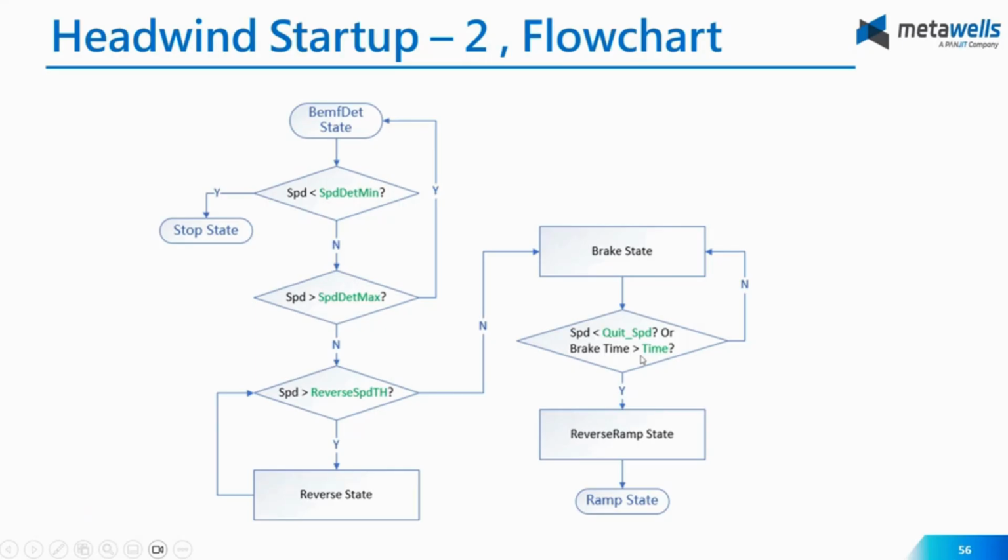In the brake mode, there are two conditions for exiting. The first condition is the speed is lower than the quit speed, or the brake time has reached the brake timeout.